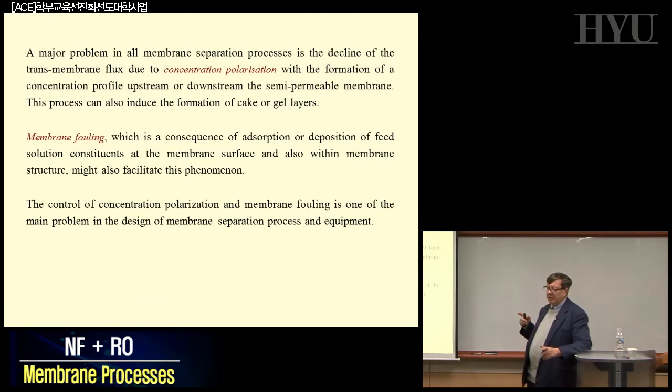In this case, the effect of the temperature polarization you can create is only related to the fact that diffusivity, viscosity, density, all the transport parameters of a solution are functions of the temperature. In some cases, increasing diffusivity or decreasing viscosity.